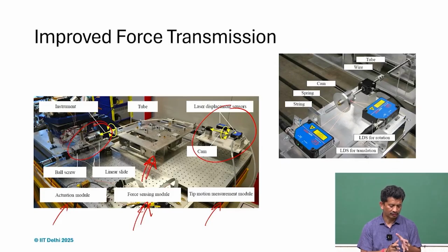and then we may be able to appreciate what goes in when we are trying to look for higher precision or repeatability. So again, it's a 6 degrees of freedom force sensing module, and we use wire flexures, just thin wires, and then how precisely the forces can be resolved, and then we can measure.